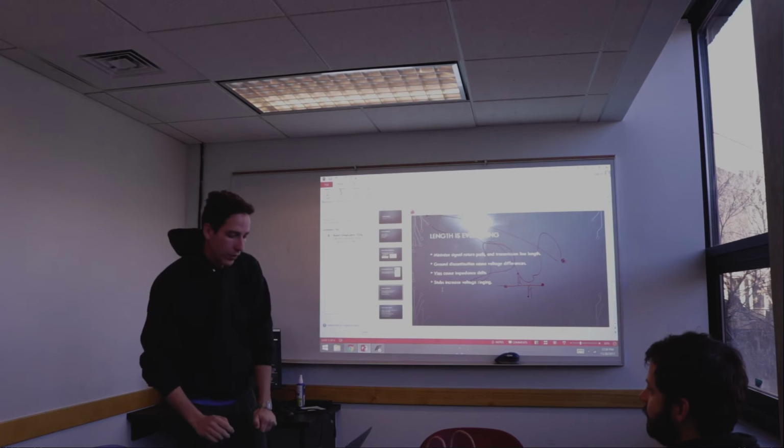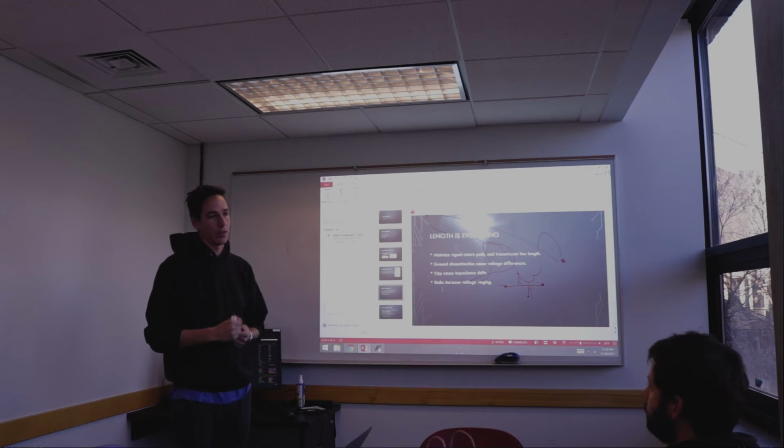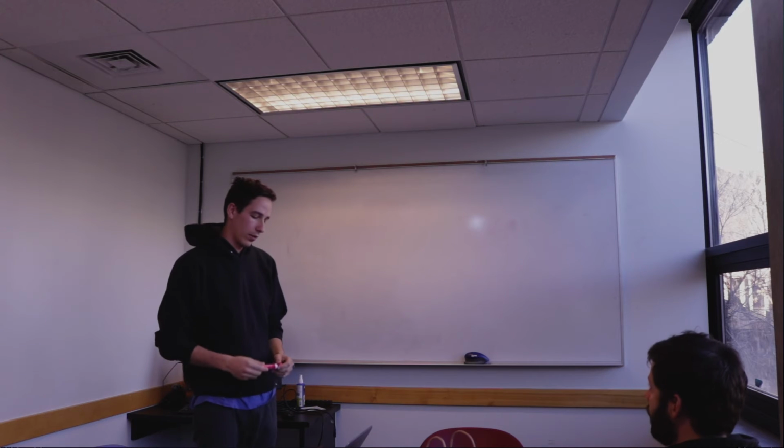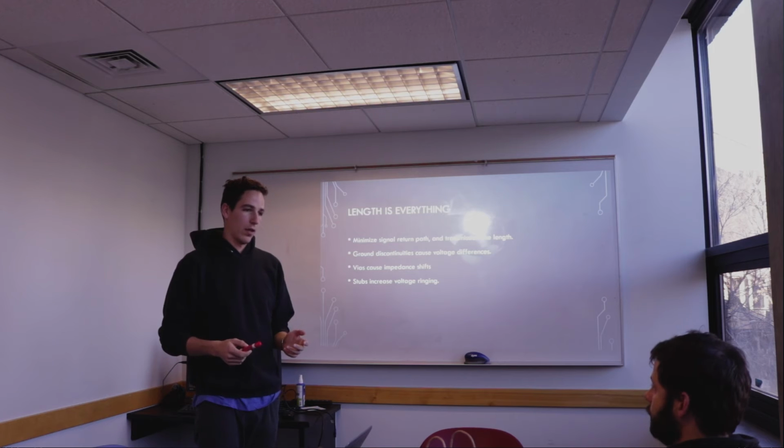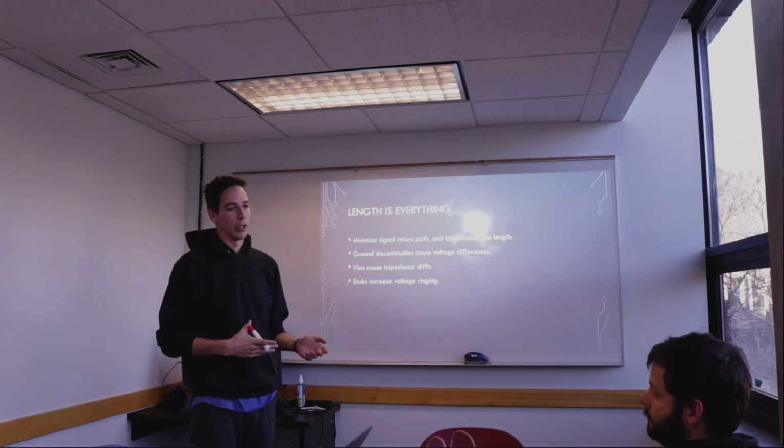The last thing was vias. Vias cause impedance changes. So when you're routing signals, keep vias to a minimum. As signal speed increases, vias cause impedance shifts, then you get more reflection.